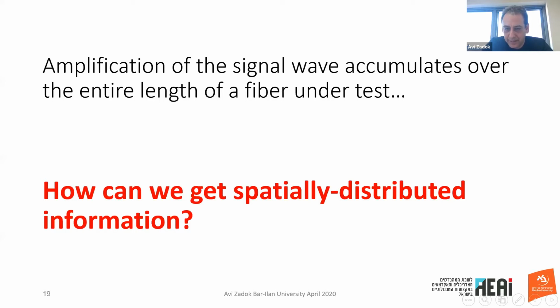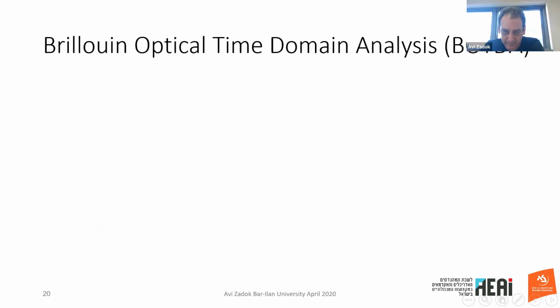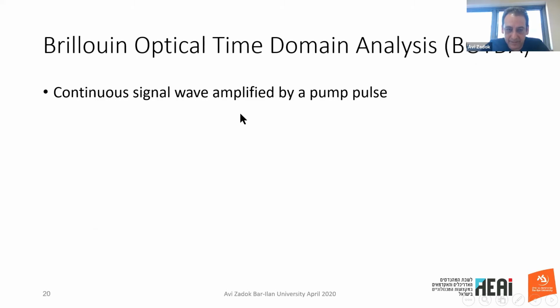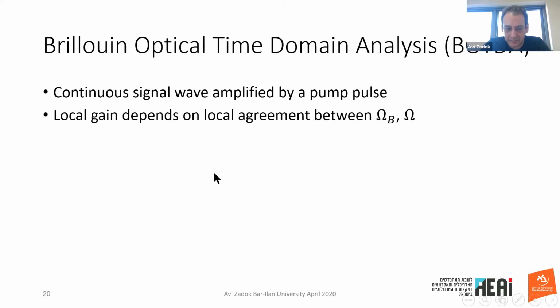And to that end, we must learn how to resolve the Brillouin gain information from one position to another. The most common protocol to do this is based on time domain analysis. This is why it is called Brillouin optical time domain analysis, or BOTDA. In these protocols, typically, we launch a signal wave that is continuous, and we send a pump pulse in the opposite direction. And these two waves, a continuous signal and a pump pulse, interact.